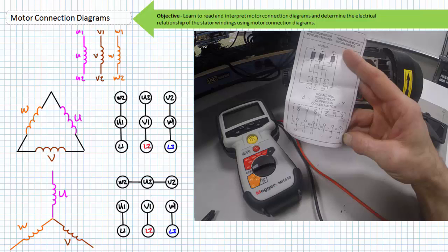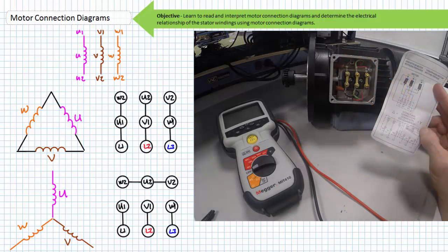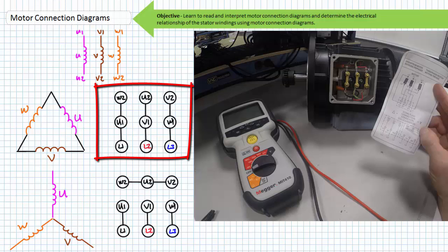The 1 and 2 terminals for individual coils are not directly across from each other on the terminal block, but rather diagonally offset from each other. The purpose behind this diagonal offset becomes readily apparent when the jumpers are used to configure this motor in a Y or delta configuration. Note when we compare this cheat sheet to the initial state of the motor, we can see that this motor came shipped in a delta configuration.